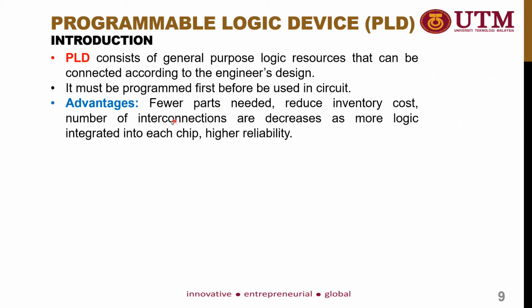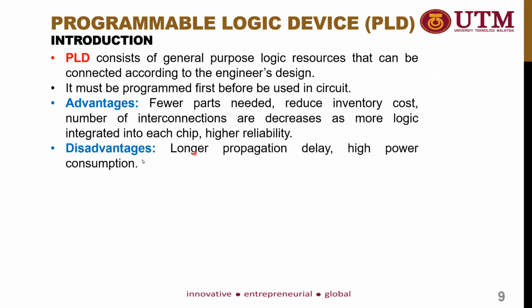So the advantage of PLD is it needs only fewer parts and it reduces inventory costs, because of the fewer parts needed. And the number of interconnections decreases as more logic is integrated into each chip, and it has higher reliability. Okay, so the disadvantages of PLD are that it has longer propagation delay and high power consumption.